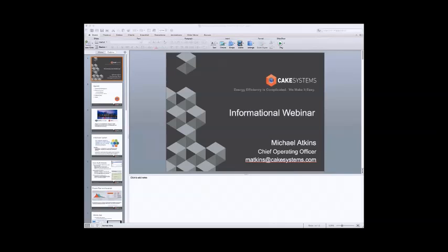We don't have the estimator built right into the system. Our protocol is for the user to go to the PVWatts calculator that's available through NREL's website for free and generate the estimated actual energy production for that site with a particular orientation, and bring that number and put it into our software so that will then be displayed in the homeowner report.